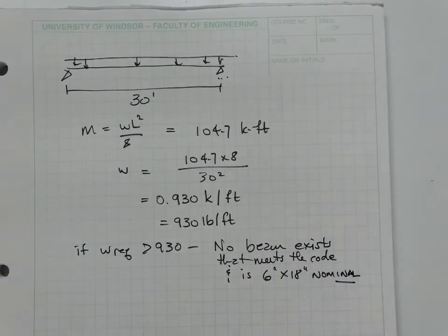That's a problem. Because very often, I mean, you can imagine if I tell the architect, hey, no problem, drop a line of columns down the center of this building, or center of this room. Now, L is cut in half, and I square it, so the load is cut by fourths. So that might not be efficient.